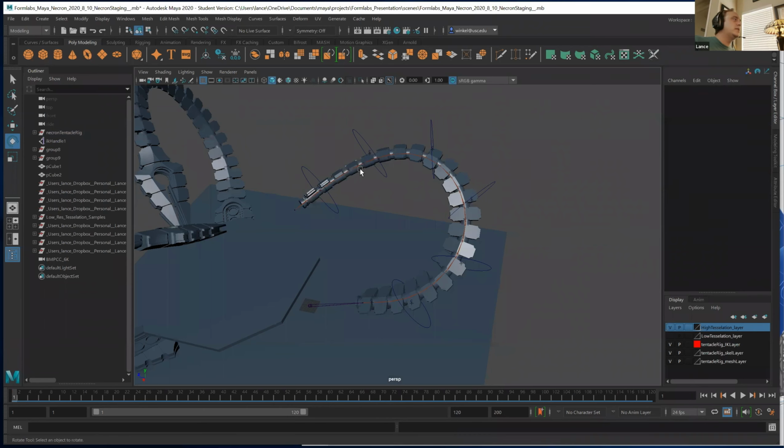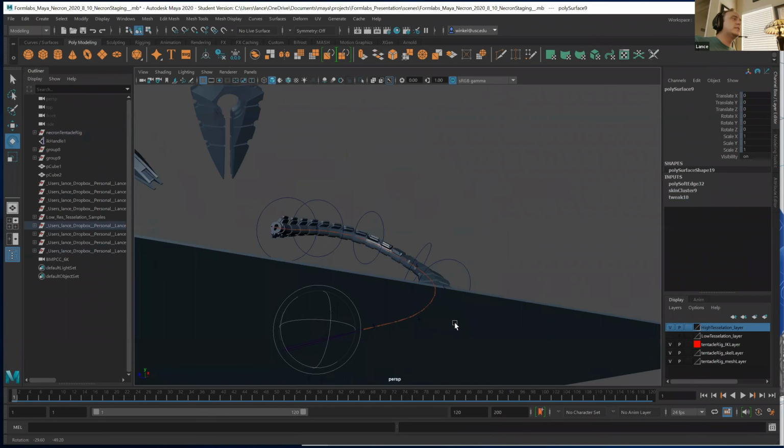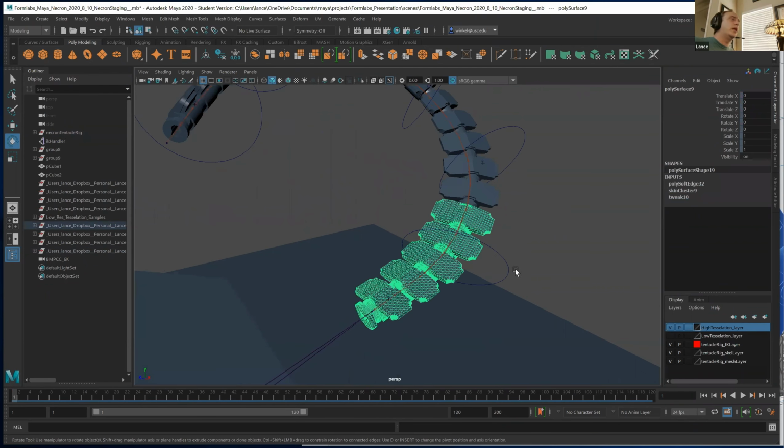like this piece. I wanna take this piece, doesn't matter which one. If I wanna export it, one of the things that's happening when you do a character rig or a deformation, all these really powerful tools that Maya has, is that technically there are two meshes happening right now. There is the deformed mesh you're seeing, but there's also, going all the way back to when you first made what we call a bind, which is that deformation that connects the skin to the skeleton.